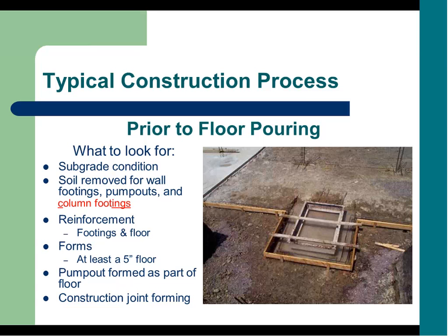Prior to floor pouring, what to look for. Again, subgrade condition, soil removed for wall footings and pump outs. Column footings, we're going to get more specifics on that with a couple other slides, but make sure that those column footings are dug and that the reinforcement is there. Reinforcement in the footings and the floor as per plan.